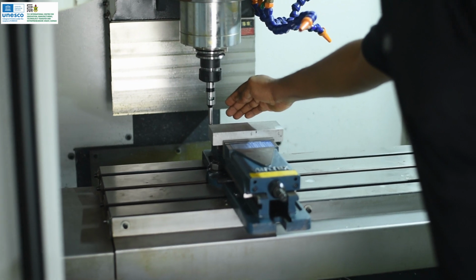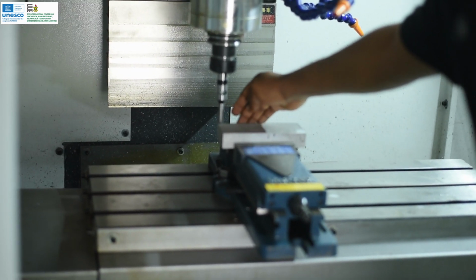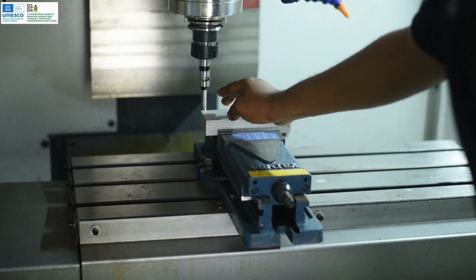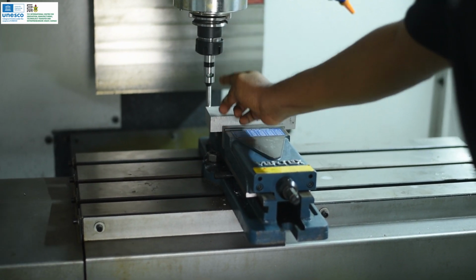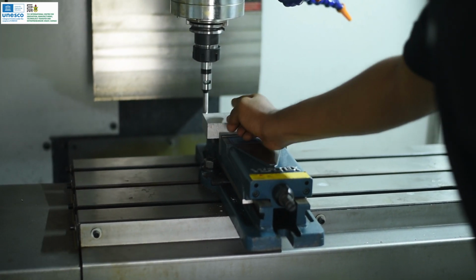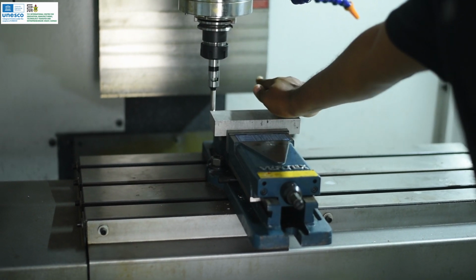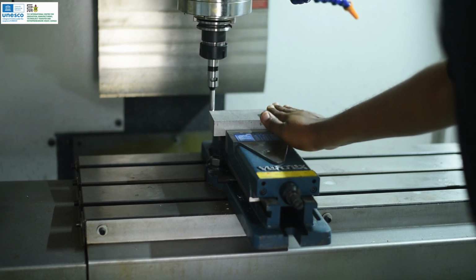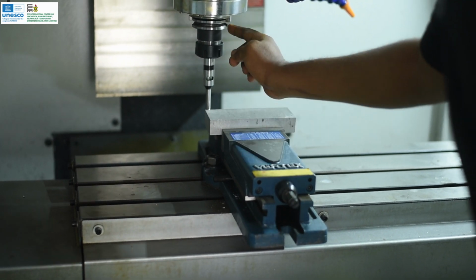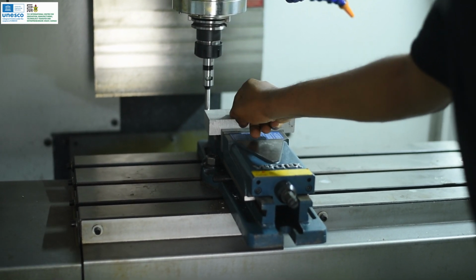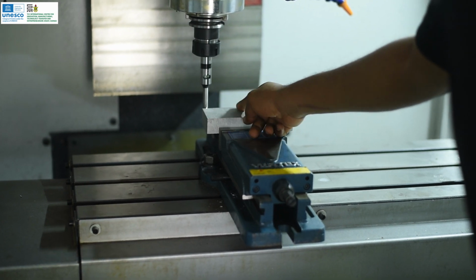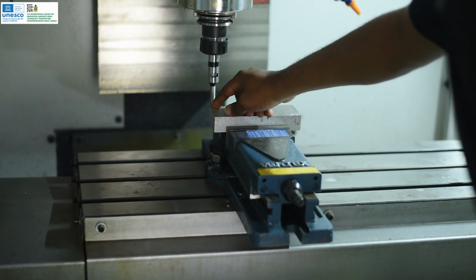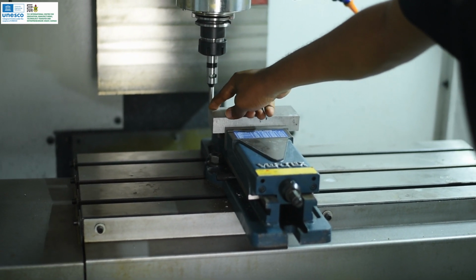If our probe is touching this part of the stock, then in order to get to the axis of the spindle, we would have to move in the positive direction, meaning y plus 5, to bring us to the axis of the machine. And so if we execute this, the probe should sit right on the edge of our workpiece.